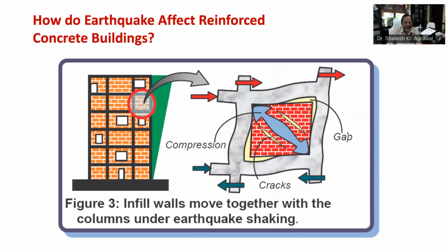Now let's see the walls. After columns and floors in RC buildings are cast and the concrete hardens, the vertical spaces between columns and floors are usually filled with masonry walls to demarcate a floor area into functional spaces, that is the rooms. These masonry walls are also called infill walls, and they are not connected to surrounding RCC columns and beams.